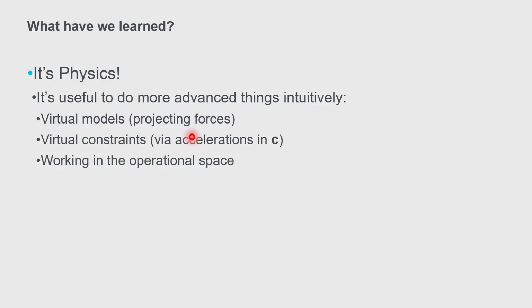You could write a simulation now. Actually, you are writing a simulation now where you say, what are the equations of motion? What are the forces that are acting here? What are the resulting angular accelerations, and so on? But you could turn this into a controller and say, well, hold on. If there's a force lambda, could I just project that force lambda into my equation of motion and send those torques to my motors? And my robot will behave as if there's a wall. And you can use that for some control purpose, to make sure your robot can move in free space but cannot go through the wall. Whenever it goes to the wall, you compute the torques. It's not a simulation, it's a controller.